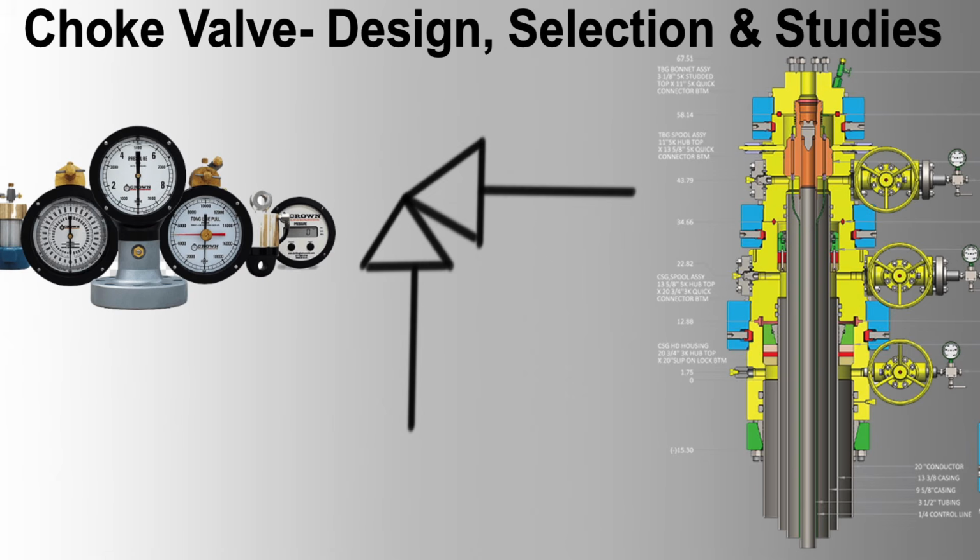2. Downstream control. Objective: to maintain a stable pressure downstream of the choke valve, which is crucial for processing and transporting fluids. Implementation: use a feedback control system to adjust the choke valve based on downstream pressure readings. Pitfalls: downstream pressure fluctuations can impact flow stability and separation processes. Improper tuning can lead to valve hunting or instability.